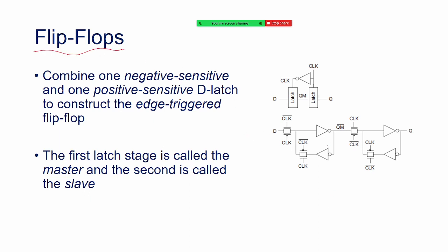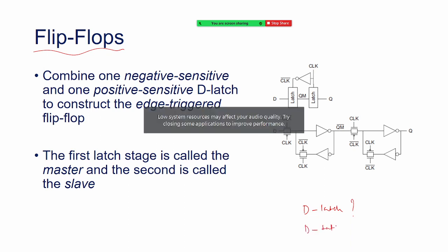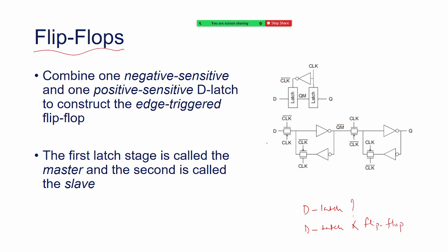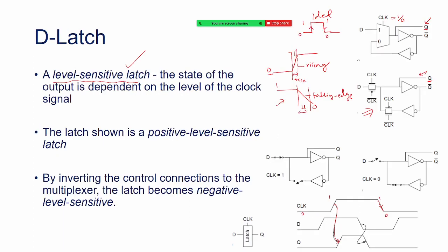One more circuit and the interview question: what is a D latch? And what is the difference between a D latch and a flip flop? So does the previous circuit have a memory? Yes, sir. Because it is holding on to that value, right? Even when the input changed here, it held on to that value. It knew what the previous state was.